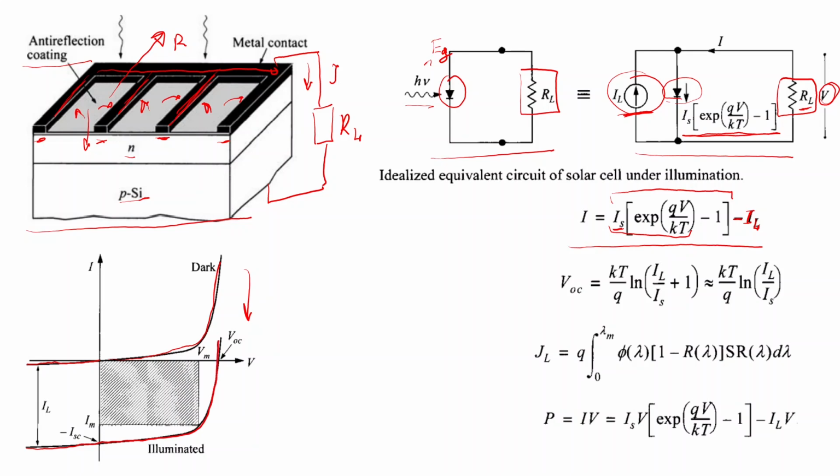And we have here this very small dark reverse current plus this photo-generated charge carrier current, like photocurrent. And they flow in the same direction. They are negative by our definition of what is positive, what is negative. That's why instead of going up, this illuminated solar cell current-voltage characteristic is shifted downwards.